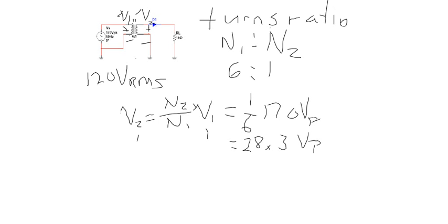Now we're going through a diode, and the diode is positioned so that I will get a positive pulse out during the positive half cycle and nothing out during the negative half cycle. And this is what we call just peak voltage going into the diode on the previous page. So my peak voltage coming out of the diode, we could also call it the load voltage, the peak at the load, because that's coming out of the diode going to the load resistance.